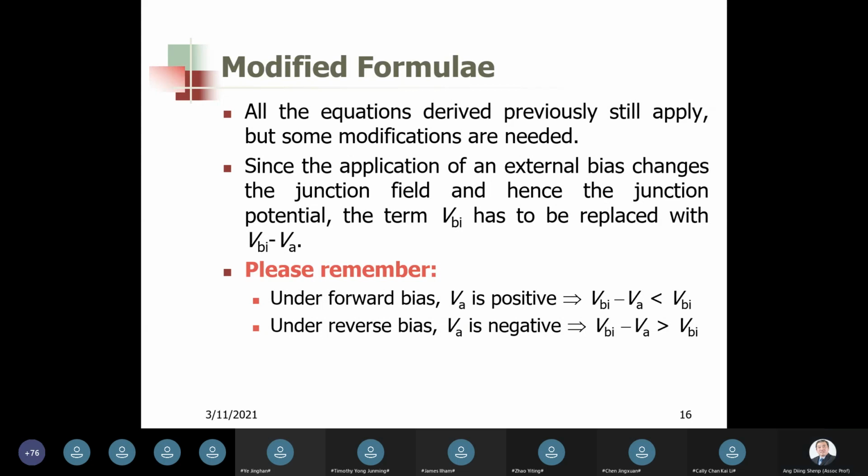It is all because of the built-in electric field and how it interacts with the applied electric field. As a result of this interaction, the net electric field can either be smaller than the built-in field or larger than the built-in field. It is these consequences that determine the rectifying behavior of the PN junction.